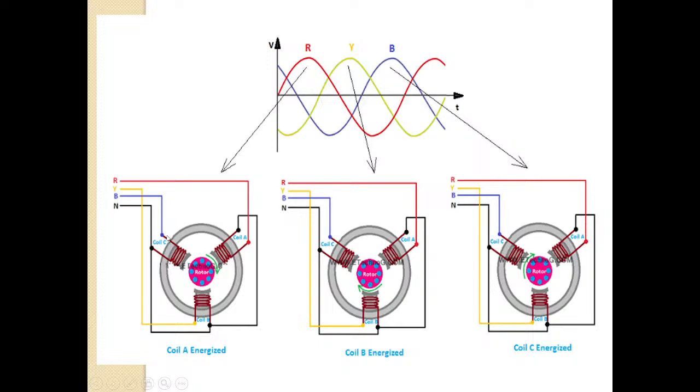When current flows through the brown wires, the stator windings, flux is induced. The flux will travel from north pole to south pole, and by traveling, it will interact with the rotor windings. So there will be electromagnetic induction, meaning mutual induction, or magnetic coupling between both the stator and the rotor.